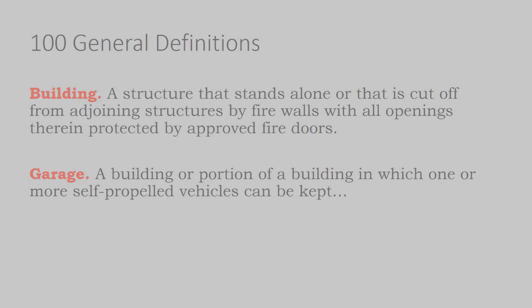While I think it's smart on ground mounts to do rapid shutdown combiner boxes, at a utility scale project where money's the bottom line, you may not have that feature. You may not be required to have that feature. Well, it depends on where you locate the equipment. If the inverter is mounted on the building wall, that's considered to be on a building. Maybe your local jurisdiction will let that slide, maybe they won't.